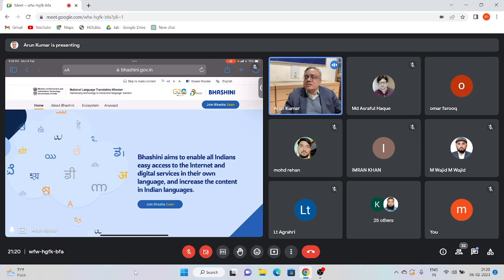Otherwise, the choice of the window duration for applications such as coding comes from the bit rate that you want to work on. If the bit rate is low, then you would go for a higher duration of the window, so that your update rate becomes lower and thereby you achieve lower bit rate. So it may come from the application also, but typically 10 to 30 milliseconds for the vocal tract resonances or vocal tract parameters, and between 2 to 5 milliseconds for the excitation part.